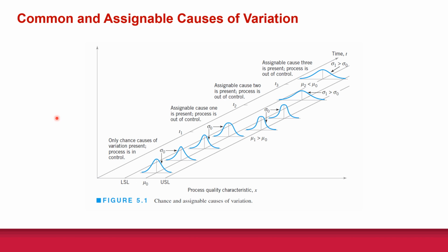And so we're producing 1,000 dumbbells a day, and we set up a regimen where every hour on the hour we sample a set of 10 dumbbells, pull them off the production line, and weigh each one, calculate the mean and the standard deviation. Then what we do is we make this time chart.